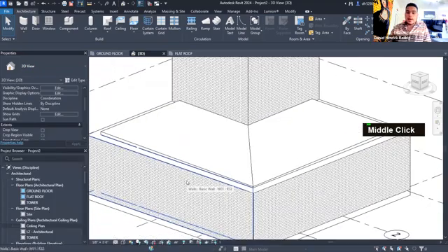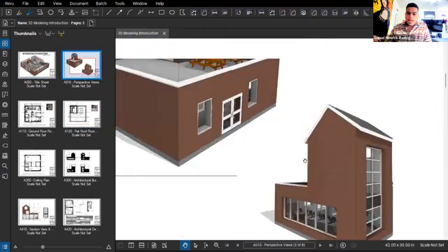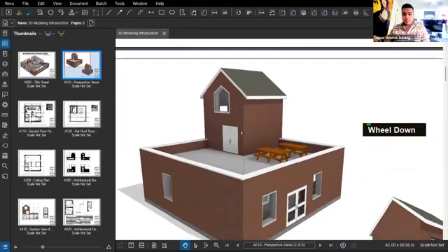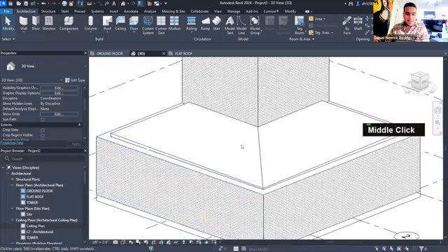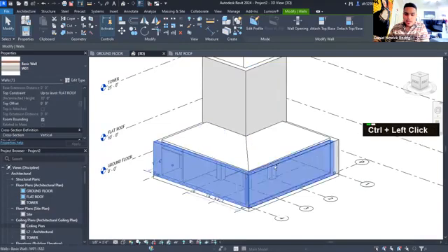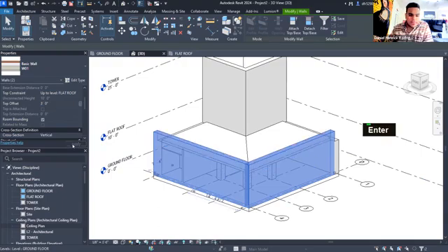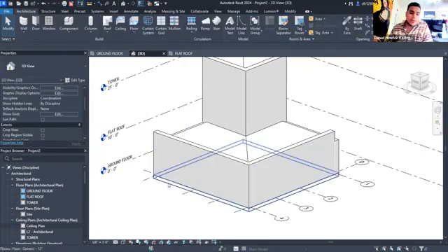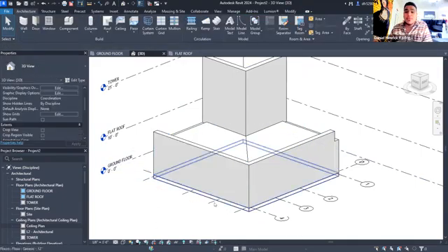So what do we do? This area, as you can see from the model here, it's an accessible area. What do accessible areas need? It's a parapet, right? You can't really be up there if there's no protection. USA. So let's make sure that we have our parapets. For the walls that are not touching the tower, we can just go ahead, click on both of these. And for the top offset, we can go ahead and add 3 feet of offset. So the wall technically still goes from the ground floor to the flat roof, but it just happens to have a 3-foot offset. Sorry if I said inch, 3-foot offset.